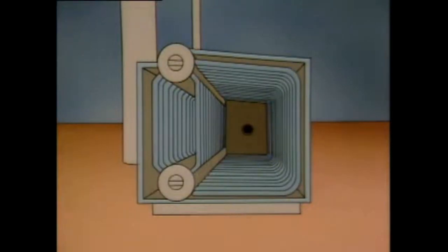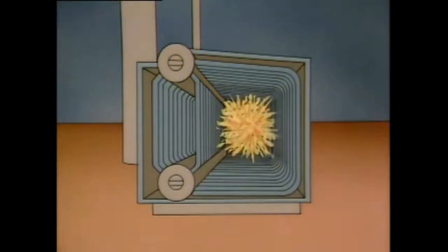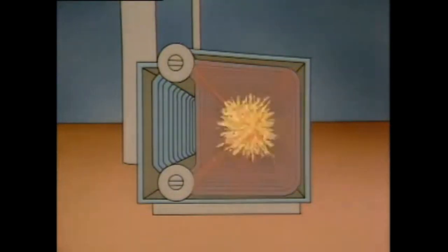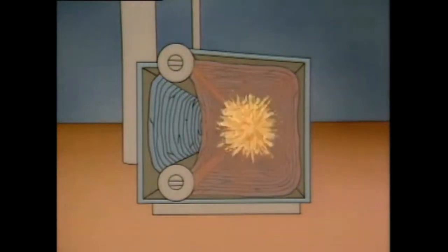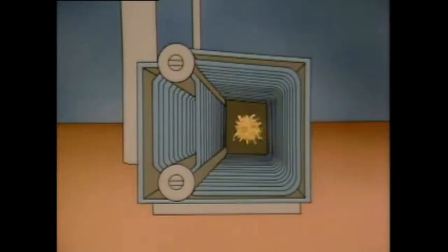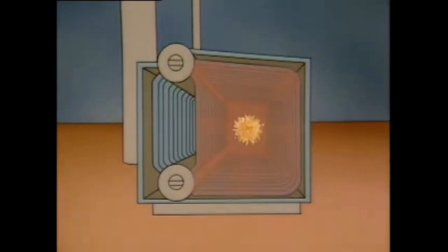The last problem we'll look at is improper warm-up. This may occur if the boiler isn't started up correctly. Water tubes and other metal parts expand when they're heated. If the boiler hasn't been operated for a while, and then it's rapidly heated, its metal parts may expand at different rates, causing some parts to bend or break. To protect the boiler, heat must be applied gradually to ensure that all the metal components expand at the same rate.